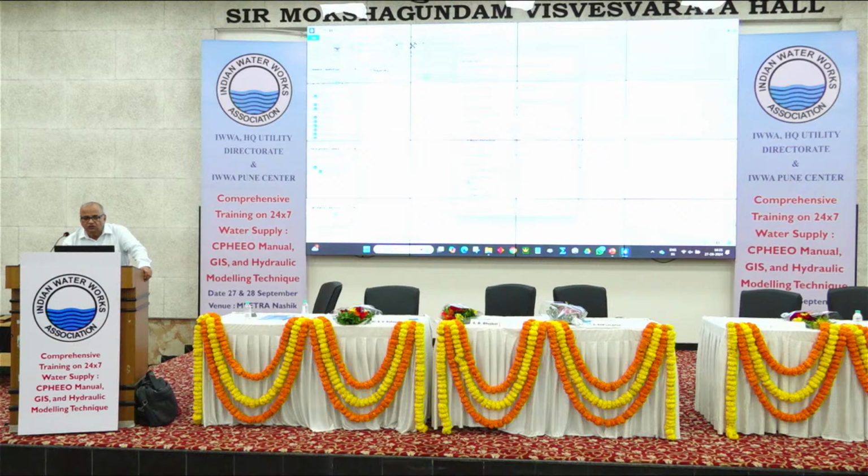And for all the nodes we have to give. If certain nodes are selected, then you have to say selection. Or if a certain selection set is created, then we have to say selection set. But in this particular case, we want this ground elevation given for all the nodes. So I'm saying yes, and it has given within a fraction of a second all these.